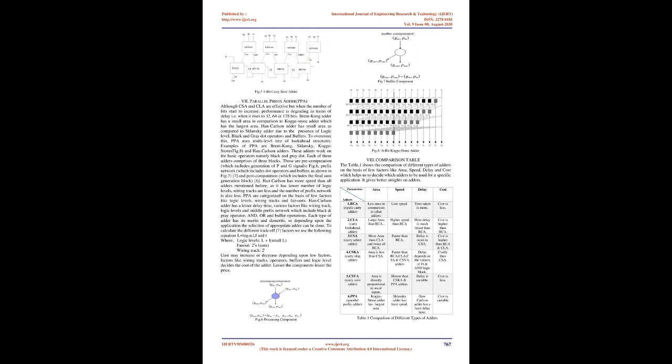After the inputs, the sum and Pi values are generated and the adder needs to AND all the Pi values. The output of the AND gate acts as the select line in the 2:1 mux. If the value of the AND gate is 1, i.e. all the Pi signals are 1, then we use CIN as the carry output and the adder skips all the FAs to process the calculation to find carry. But if the AND gate value is 0, i.e. any one of the Pi signals is 0, then the carry is calculated like in RCA, that is, carry is calculated from LSB to MSB.